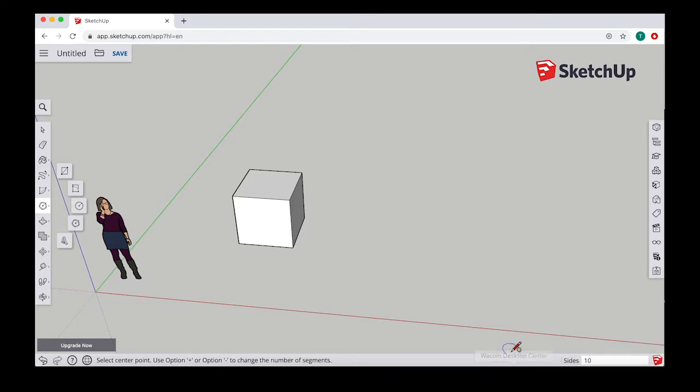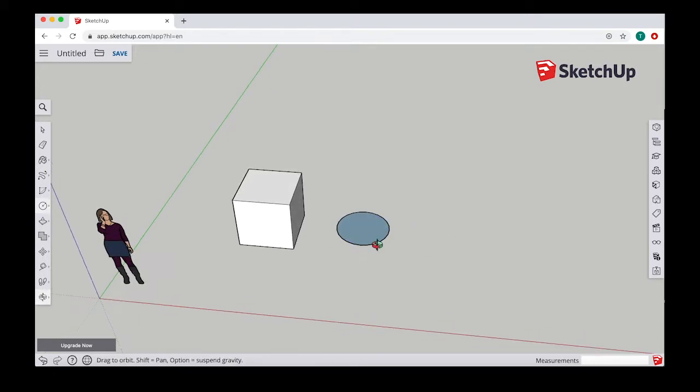So now I'll be going over how to use the circles and polygons tool. You'll find this tool in the rectangle submenu, and the circle tool will just be the icon with the circle in it, and you can click that. Left click once, and then you'll be able to draw, and you can change the radius of it by typing in or just by dragging your mouse. So we'll just do like a 500mm radius, and then you have a circle just drawn flat on the ground.